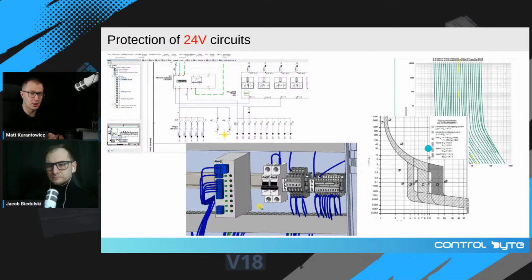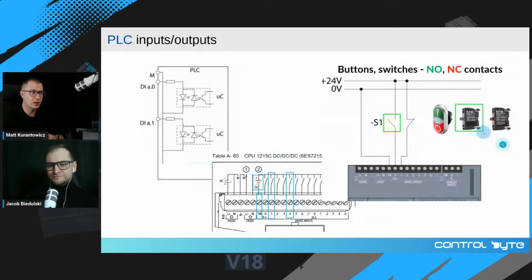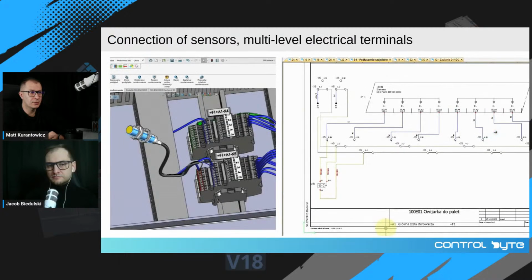How to use fuses and protections for that. How to connect inputs and outputs of PLC, and also how to even connect sensors to the inputs via terminal blocks.